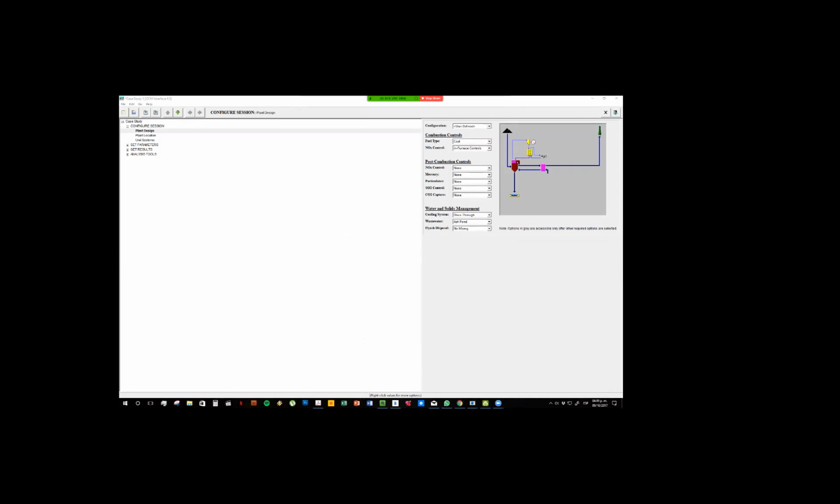Okay, so as I was telling, the NOx control is in that, but we have post-combustion control too. So we have different types for different pollutants. For example, the NOx control after the combustion is called a hot side SCR. Mercury we can control with carbon injection.